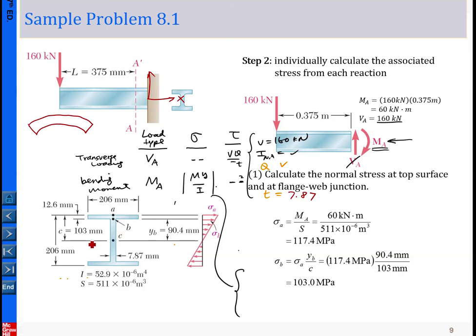If the bending applies in this way, then right away you should know this is the neutral axis, the symmetric plane about which that's the neutral axis. Given the bending curves down, the lower portion will be in compression and the upper portion will be in tension.